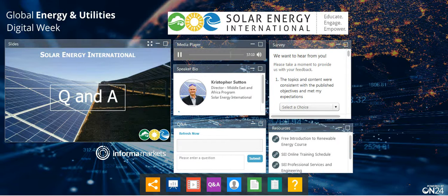Okay, so if there's no grid, let's think about our systems again. If I'm grid connected, if I have a normal grid synchronizing inverter with no batteries, then when the grid fails or the grid goes offline, that inverter also goes offline. So if I don't have any backup power, it's a non-battery system with a normal grid synchronizing inverter, there's no power, even if it's full sun daytime, if the inverter's offline.